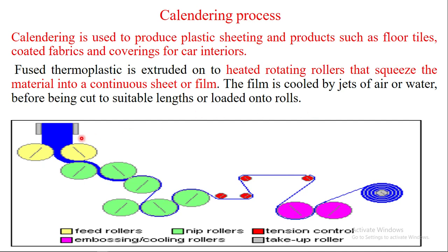See these ones? Those are rollers. By using different rollers at different levels, the plastics are heated. Then the rollers squeeze the plastics, which reduces their thickness. Then plastic sheets that look like hairs are produced. This process is known as the calendering process.